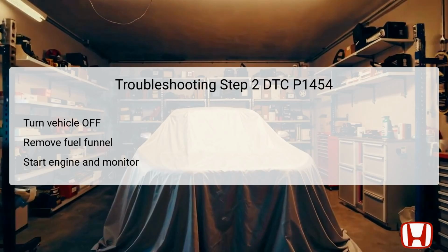In the third troubleshooting step, turn the vehicle to the off/lock mode to safely perform the next procedures. After this, turn the vehicle back to the on mode. Clear the DTC once more using the HDS. Next, disconnect the EVAP canister vent hose from the EVAP canister, which allows you to investigate any possible blockages more effectively.